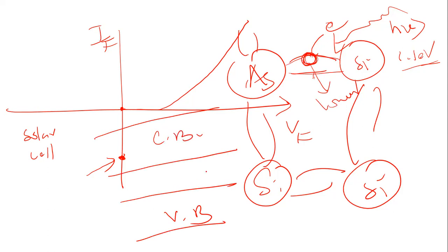So by absorption of these photons, if the band gap energy is 1.1 electron volt and the photon energy h nu is greater than this band gap, electrons will be excited from the valence band to become free electrons and holes. And as there is an empty space at the lower energy state, the electron will be more comfortable lying in the lowest energy state. Then the electron will fall back and undergo the process called recombination. The electron will again participate in the chemical bonding. Right.